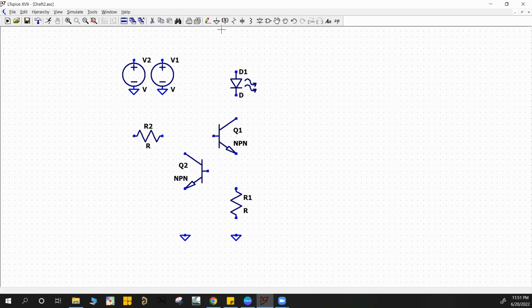So now we have all the circuit, all the components. So all we need to do is just connect them, right? So we just take the wire, we connect this through here, you connect this through here, connect the transistor, connect the resistor. You could actually just go through it. LTspice automatically fixes that, so it doesn't draw over the component. And then the same thing over here. Oops, I went a little too far. Got a little too excited there. And then we're gonna connect it over here, and boom.